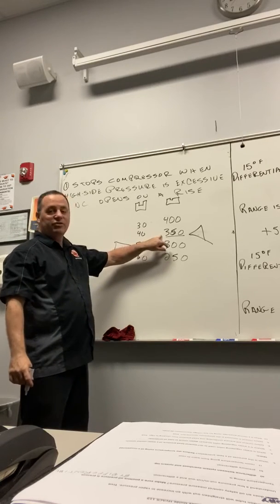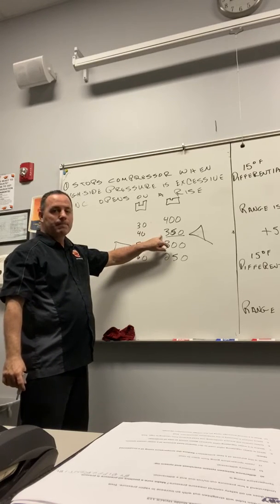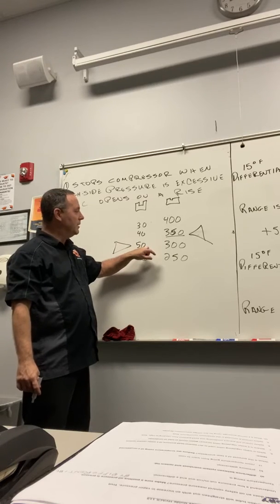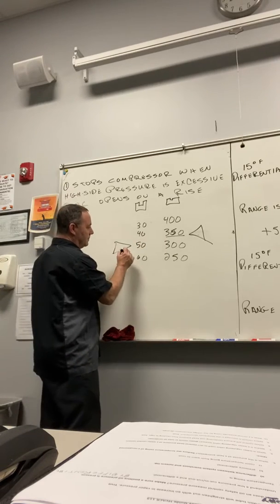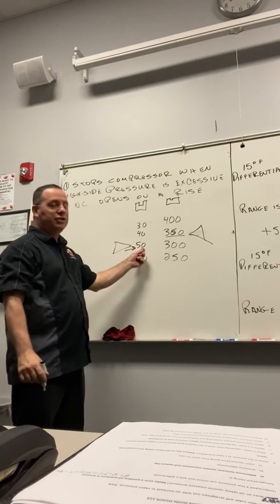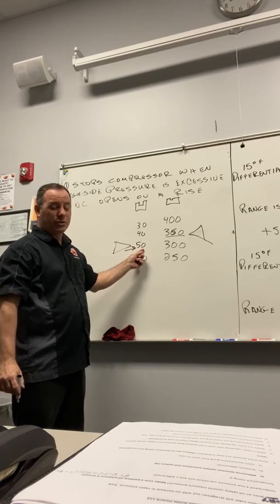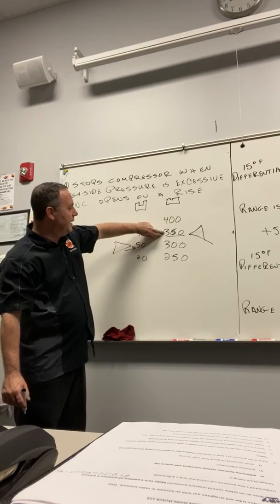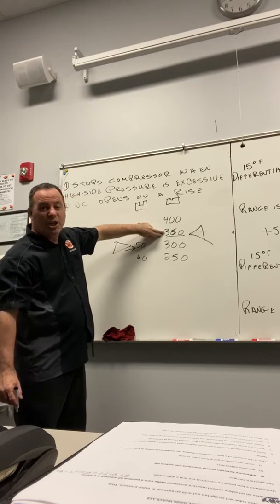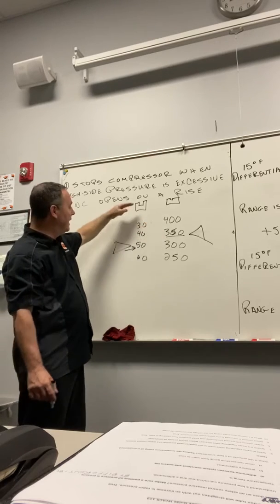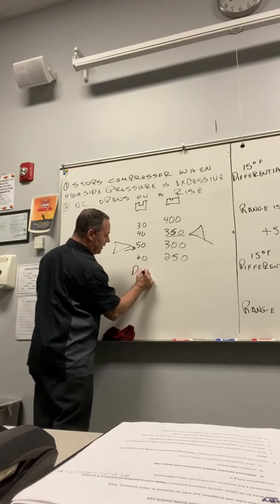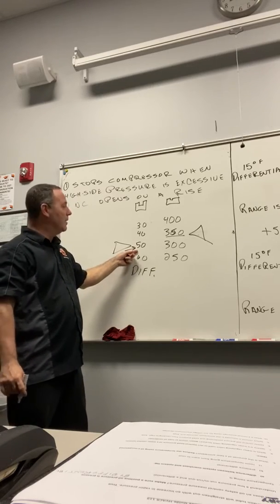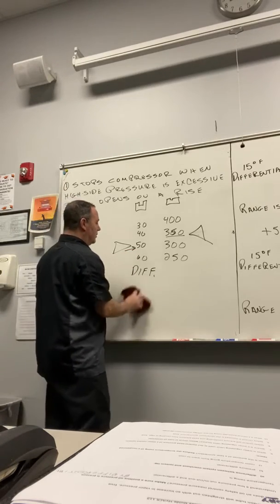That means it cuts out at 350, and it'll cut back in at 300, because you're going to have to adjust it by the differential, okay? So you want it to cut out at 350, and I want it to cut in at 300. So over here is the differential. It'll say I have to do 50. That's the way it works. That's on the high ones, okay?